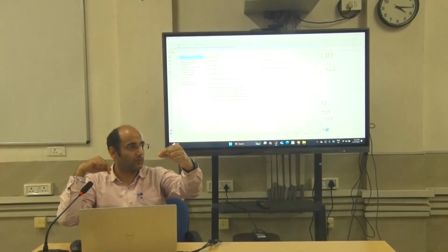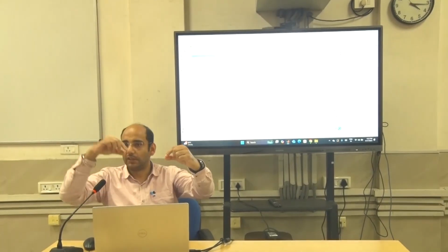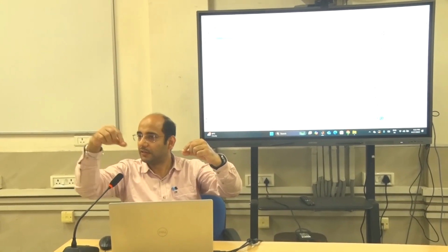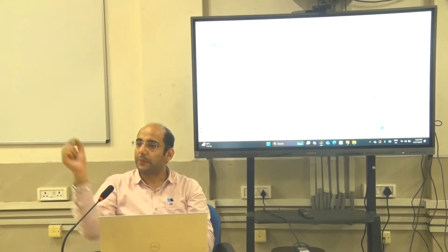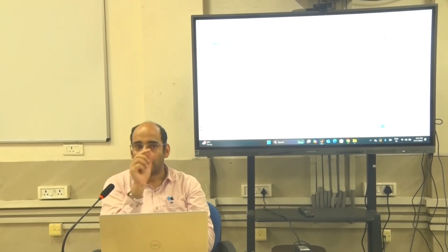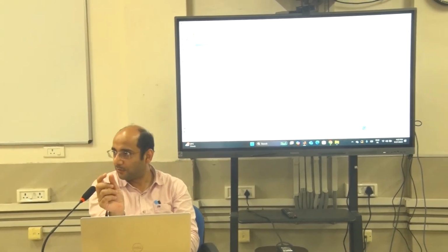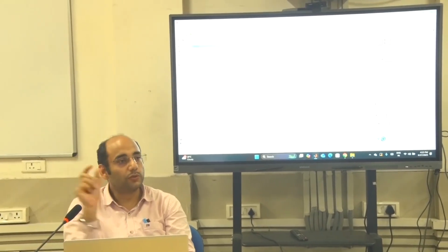That means at omega t equal to 0, omega t equal to pi, omega t equal to 2 pi. That means you are doing the sampling where? At 0, next 0, next 0. If you do this kind of sampling and you run the simulation, what would you get? You will get 0, 0, 0 connected by a straight line.